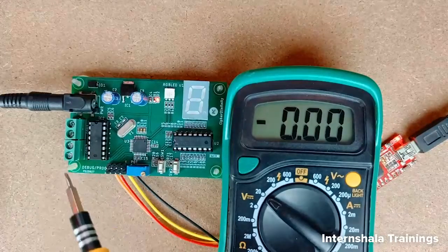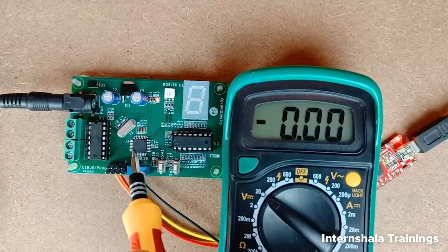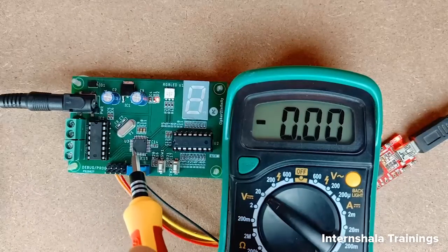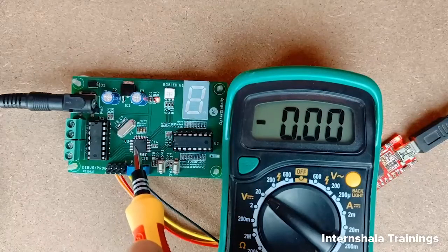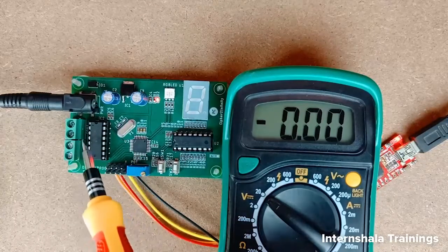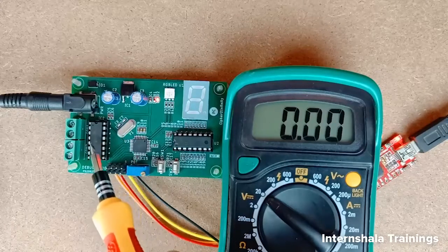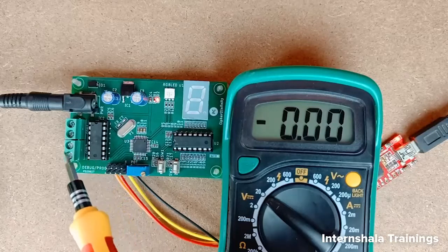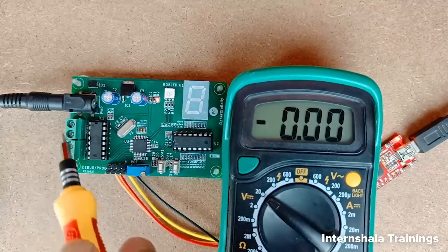So what we are doing, we are controlling the enable pin with the help of the PWM pins which are present on the controller. Okay, you already know that we have connected the PWM pins of the controller to the enable pins of this L293D IC. And by using the PWM feature of this controller, we are controlling the enable pins of both the channels. Okay, and that's how basically we are controlling the speed of the motor.